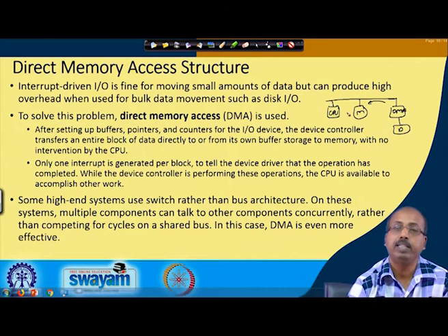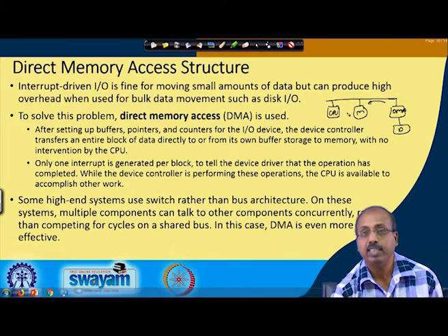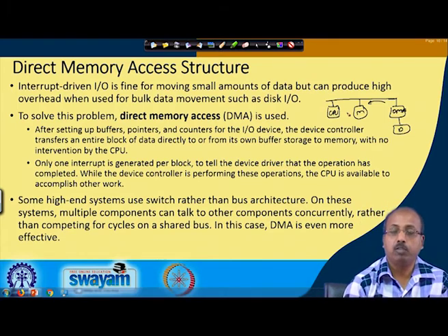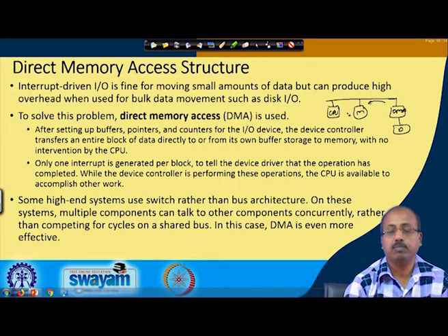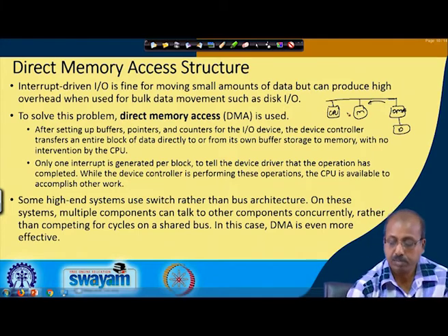So, now the CPU and DMA start competing for the bus access, and that restricts the system performance. Normally, the strategy that is followed is that DMA is given lower preference than CPU, and whenever the CPU is not using the bus, then only the DMA controller will be using the bus for the transfer. This is called cycle stealing. However, some systems, to improve the performance further, have some sort of switch connection.